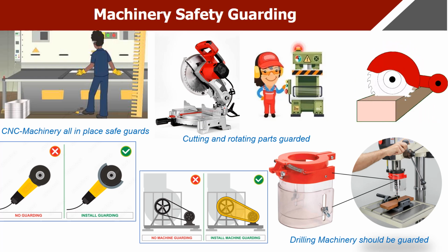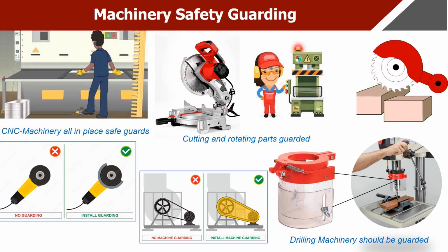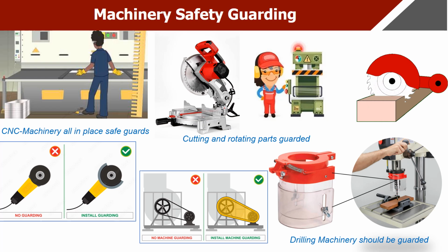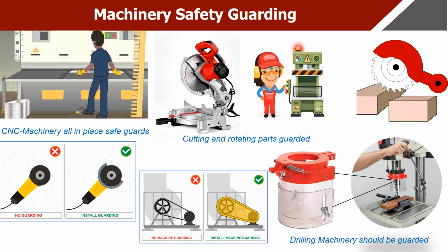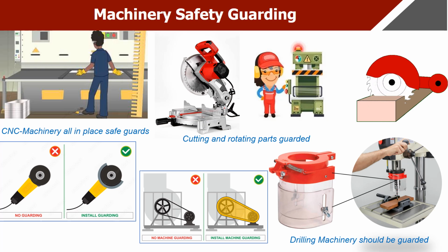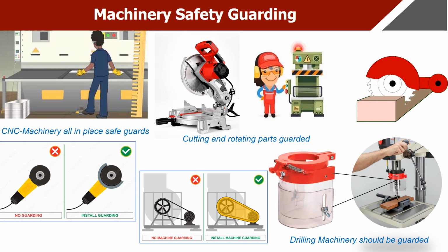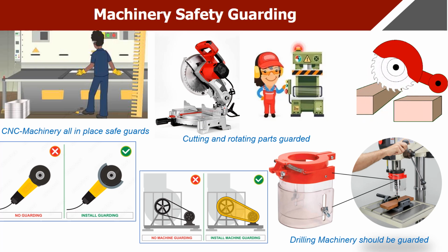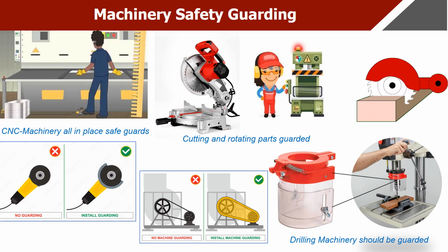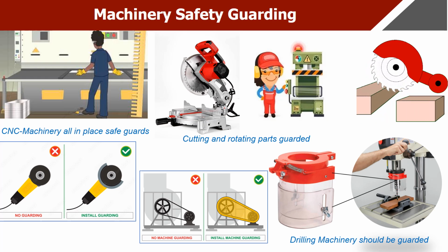10 steps for machine safety, Singapore WSH. 1. Follow Workplace Safety and Health (WSH) procedures at all times. 2. Wear proper personal protective equipment (PPE). 3. Inspect machine before use. 4. Ensure all machine guards are in place and functioning. 5. Do not operate faulty or damaged machines. 6. Keep hands and body away from moving parts.